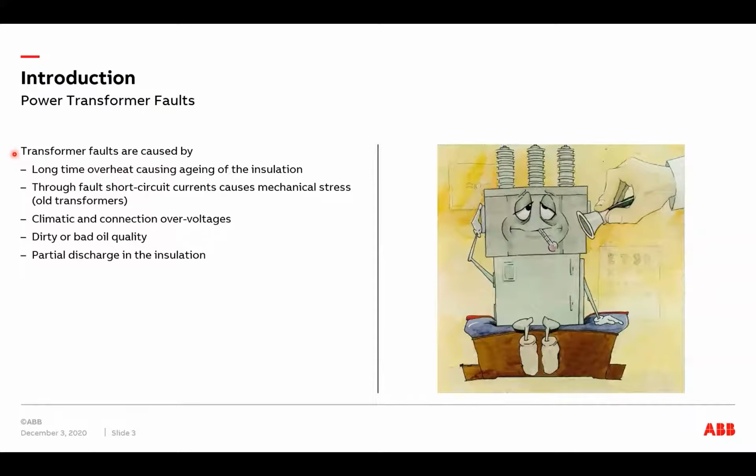And when there's a short circuit downstream, there will be a high current flowing through the power transformer. The high current will cause a mechanical stress on the windings, which in turn will have a negative impact on the winding insulation.